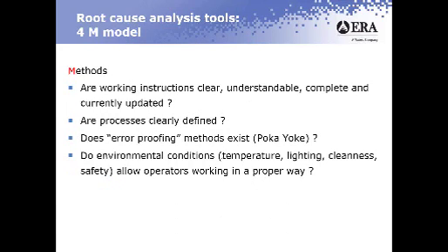All right. With methods, are you working with clear instructions? Are there procedures that are supposed to be followed? Whether they're work procedures or SOPs, are they understandable? Are they complete? Are they currently updated? Or is somebody using an old standard? Are processes clearly defined? Does the individual or individuals know what their role is in these processes and know what they're responsible for? Do error-proofing methods exist? From a Japanese term, it's called poka-yoke, where you try to make sure that your processes and your methods are error-proof so that mistakes can't be made.